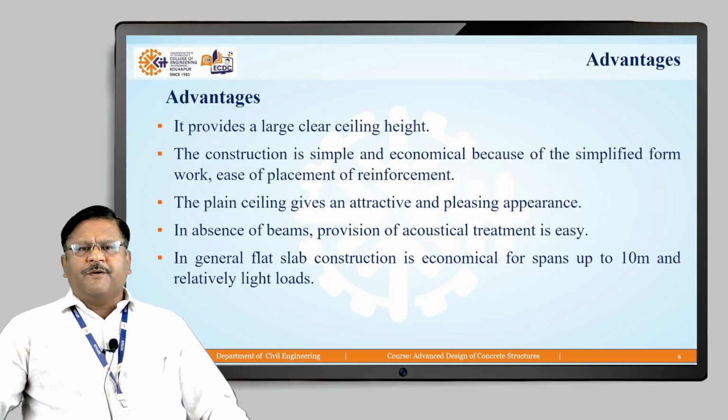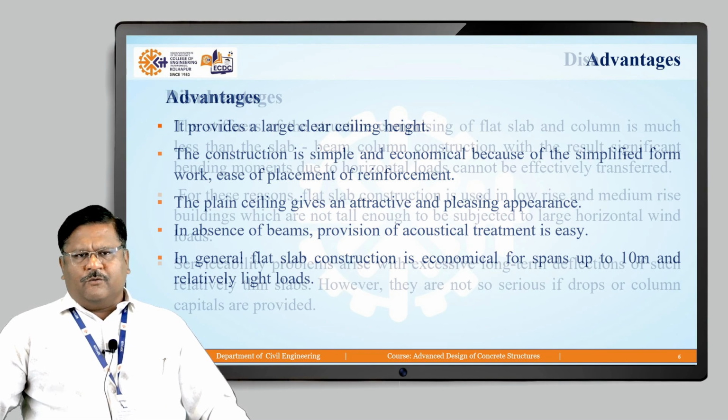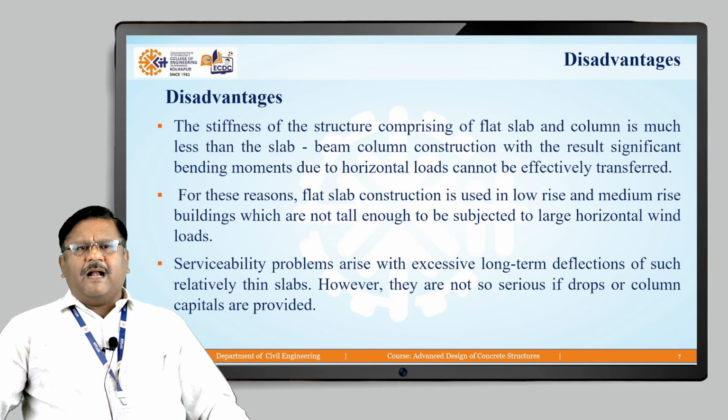Fourth, in the absence of beams, provision of acoustic treatment is very easy. And last, in general, flat slab construction is economical for spans up to 10 meters and relatively light loads. Means for heavier loads we cannot design it economically. We are able to design the flat slab, but generally it is economical up to 10 meter span and relatively light loads.